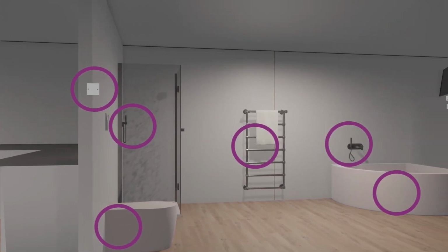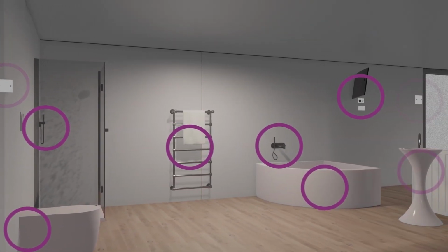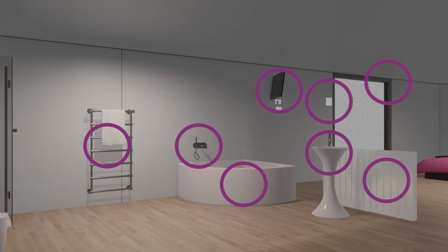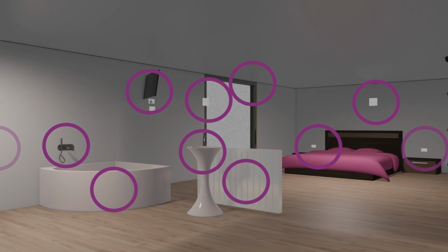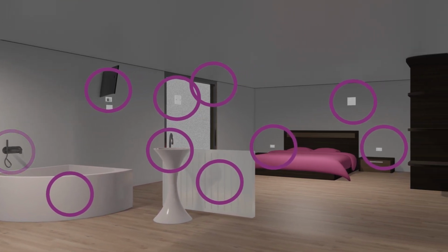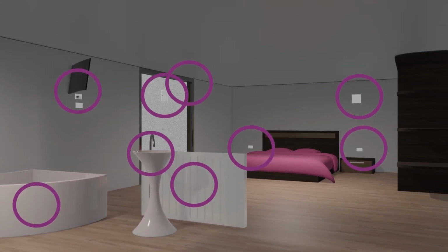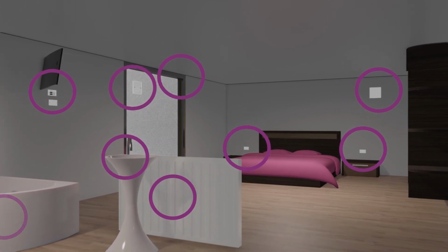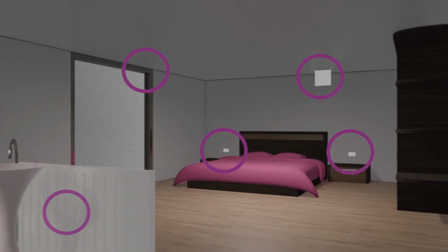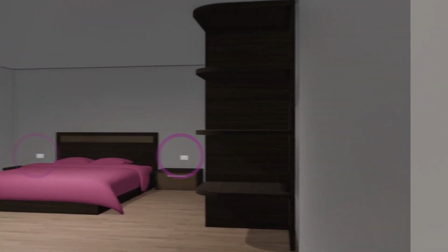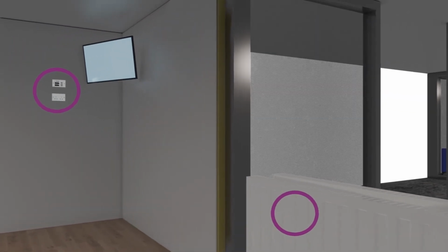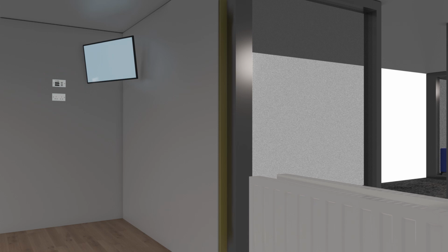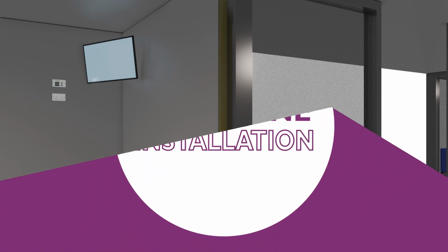This process can be speeded up somewhat by proprietary seals and components, but this can increase costs and complicate supply chains. Using a fully adhered external barrier removes this problem completely, ensuring that the panels arrive in position perfectly sealed and the performance in practice matches the design criteria without requiring any unusual measures or specialist products during the construction process.